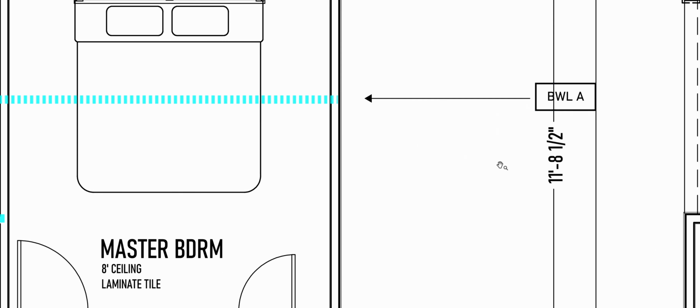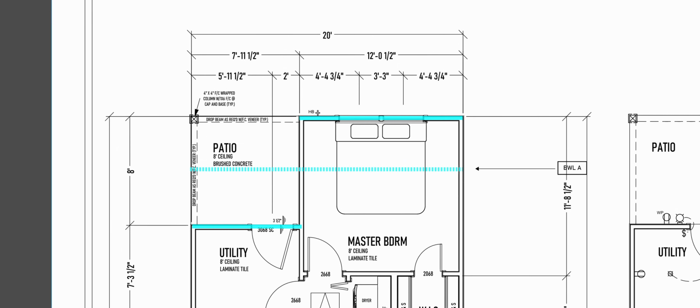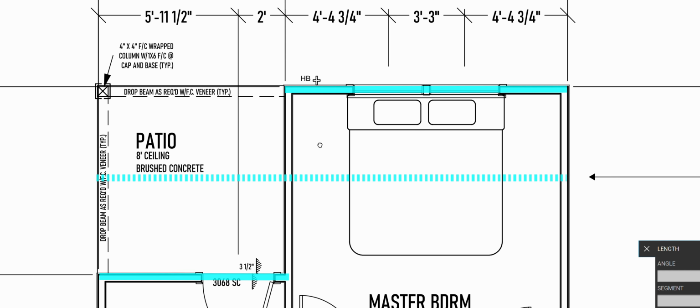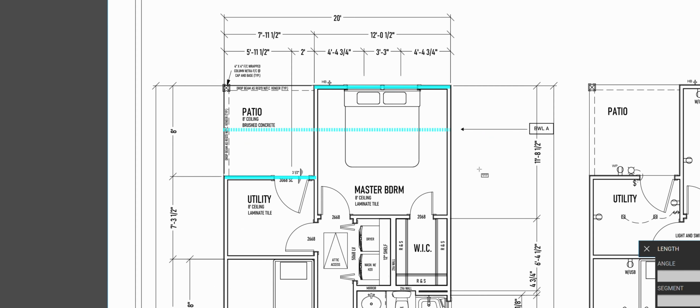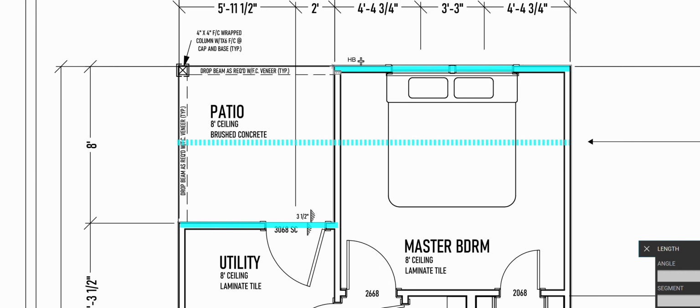So, well, how is that my braced wall line if that's not where my walls are? Well, that's because the rule is, as long as, because houses are never like boxy and perfect shapes, my braced wall line, which can be a theoretical line, as long as my real walls don't deviate more than 4 feet from that line, in this case I'm exactly 4 feet because this is an 8-foot dimension offset. So as long as they don't deviate more than 4 feet from my theoretical line, I get to count that wall as part of my braced wall line.